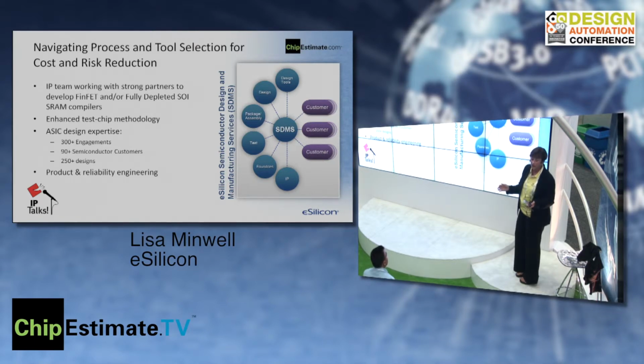We have an example of a particular design where in this chip there was a particular SRAM instance that was repeated 1,000 times. And in this one instance, if we could remove a function that wasn't being used in a standard off-the-shelf compiler, we reduced the area significantly. And it was a direct, very large savings for that customer. But to do that, you have to mitigate your risk as well by starting with something that is silicon proven and by not affecting any of the paths, any of the aspects in the sense amplifier, the timing paths, etc.